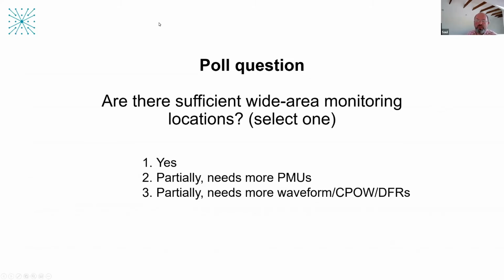We do work with transmission, but also in offshore wind generation, and we're working with developers like Vattenfall right now on putting more distributed but critically permanent and synchronous power quality monitoring in these wind farms, because of course these effects coming onto the grid may be seen, as with your Dominion slides, in a kind of aggregate form at the grid connection, but even that isn't good enough, because you've got to go beyond that connection to each individual inverter and say, okay, where's the source of this problem actually coming from? Because it could be a specific turbine or a specific set of electromechanical problems that are occurring out there.